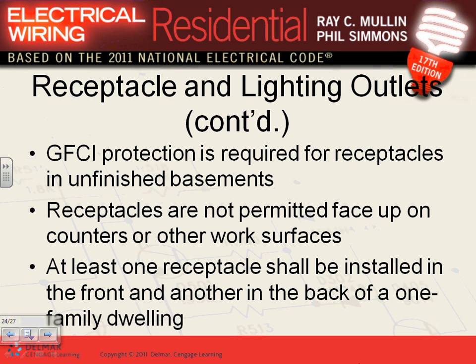All receptacles, and all branch circuits, have to be arc fault circuit interrupter protected, except the following. Arc fault circuit interrupter, guys. Except the following: bathroom, anything in the bathroom, excluded. Anything in the kitchen, excluded from arc fault. Anything in unfinished basement, excluded. Outdoor, excluded. Garage, excluded. Other than that, every single circuit in your house in residential has to be arc fault circuit interrupter.